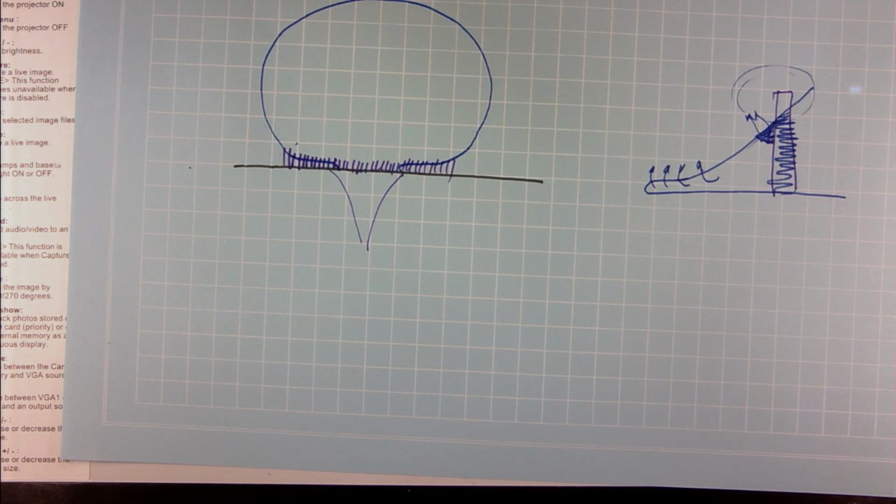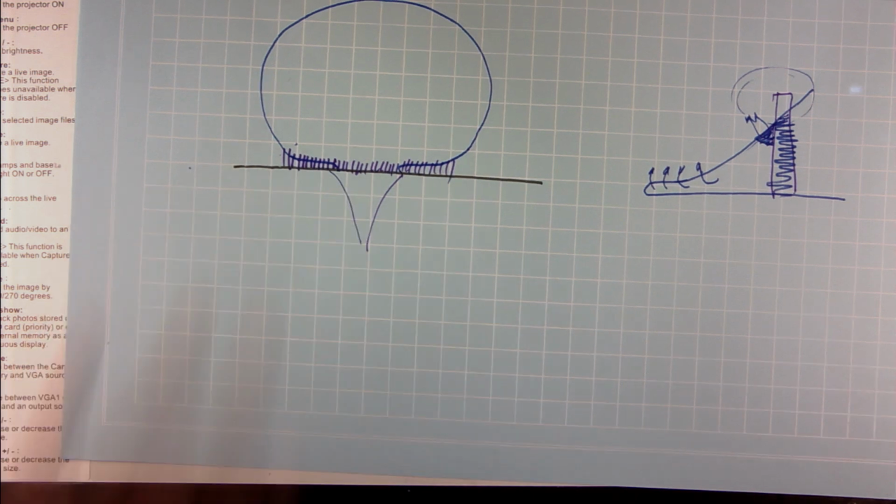So, there is a theory called wickability that treats these surfaces as nanoporous surfaces, which means if I form nanobubbles and these nanobubbles keep feeding into this big bubble, then maybe the wickability of that structure makes sense, because as soon as a nanobubble forms and leaves, the wickability determines how fast the liquid goes and fills it up before the next nanobubble can form. So, there are probably unknown issues that we have not looked at, but from the current experiments that we have, this is how the structure looks right now. You have a bunch of these tiny hairs and you have this big bubble on top of that. Does that make sense?